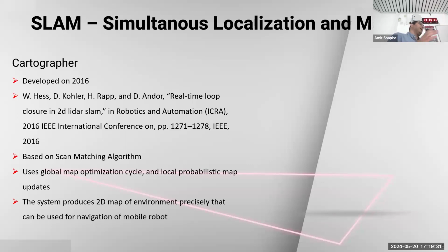One is the local planning, which is a probabilistic map. And then there is the global mapping, in which it finds where it was and does some kind of loop closure. So when it gets back to a position that it has already been in, then it knows where it is, and removes the error, reduces the error.